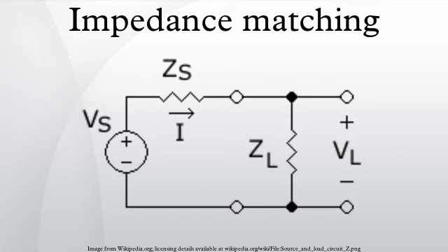Theory: impedance is the opposition by a system to the flow of energy from a source. For constant signals, this impedance can also be constant. For varying signals, it usually changes with frequency. The energy involved can be electrical, mechanical, magnetic or thermal. The concept of electrical impedance is perhaps the most commonly known. Electrical impedance, like electrical resistance, is measured in ohms.